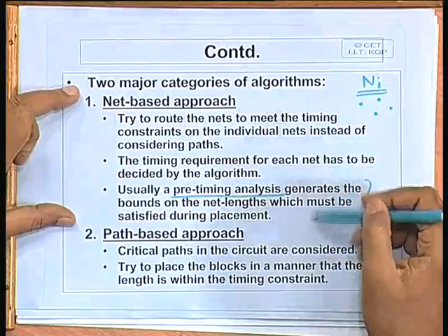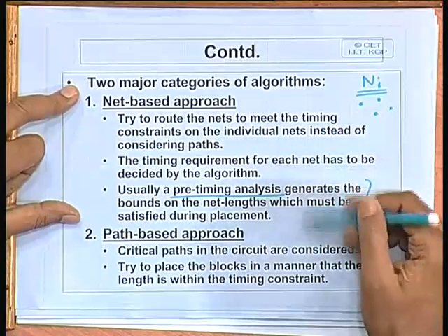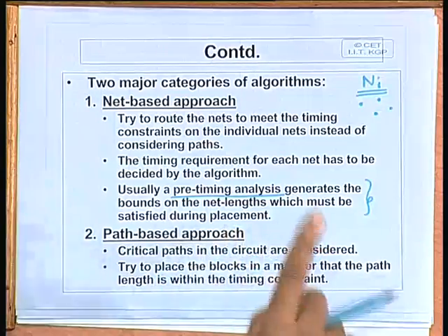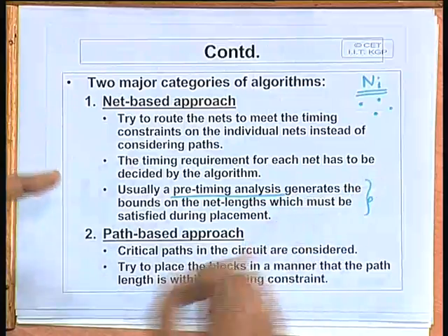So these two approaches are also algorithms for placement. See, this kind of an algorithm cannot be a placement algorithm individually. Here placement and routing should go hand in hand. Just giving an estimate using the semi perimeter method or anything will not tell you exactly what the real delay is. You will have to find out the exact routing path and see whether the timing constraints are really met. So, for performance driven design, placement and routing must go on together.